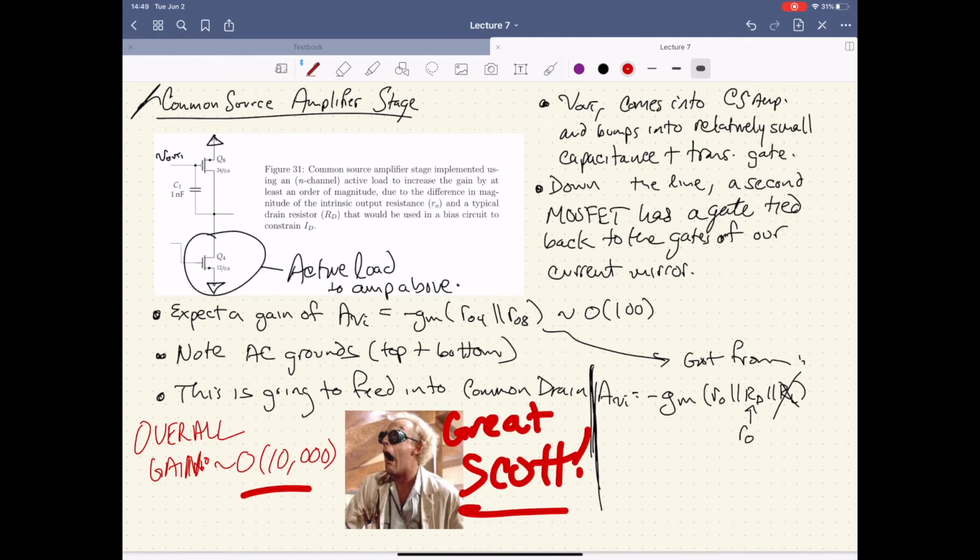So something to keep in mind when we're dealing with op amps, they're very powerful devices. But one of the problems that we have now, we've gotten all this gain, but what do we have for our output resistance at the moment? It's not looking pretty, guys. So here's our CS block. If we look at R out, this is equal to RD, which is RO at this point. So we're not powerful enough to really do anything. Whoops. So we gotta remedy that.